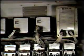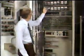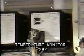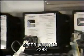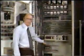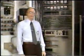Here is your instructor. The engine is controlled by several solid-state electronic devices located here in the control console. Located across the back of the console, as an example, are the engine temperature monitor, labeled Z282, the speed monitor, Z283, the main fuel actuator control, Z244, and the ramp generator in the upper left-hand corner, Z249. Down here is the speed and load sensing control, Z251. Now let's take a closer look at the functions of each of these black boxes.